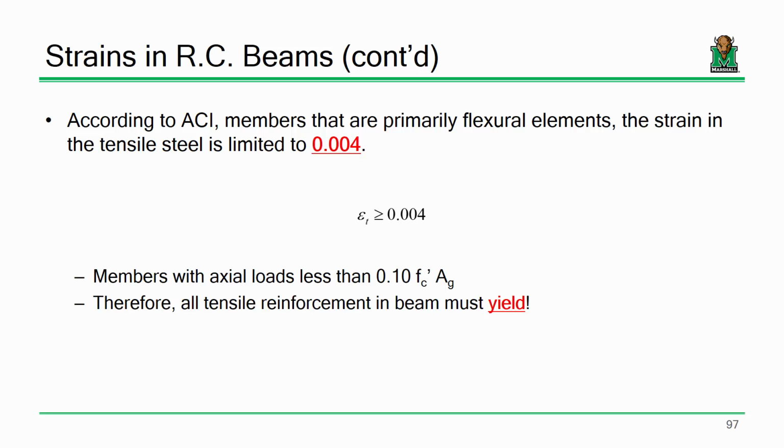When that concrete fails in compression, it goes quick. Boom, right? That's how concrete fails in compression. Now, what happens when steel yields? It just gets a little longer. So what, right? I'm not saying it's desirable, but if we're being honest, steel experiencing a little bit of yielding is a whole lot better than a concrete element experiencing crushing strains.